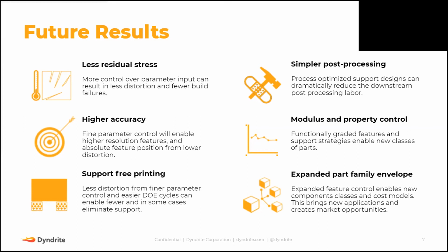Yeah, perhaps this is a sidebar. One thing we could probably do as an industry is standardize how we refer to things a little. So things such as stripes, checkerboard, meander, we refer to as scan strategies overall for the 2D area. What we refer to at Renishaw as a scan style is individual vector types. So whether that be borders, hatching, downskin borders, downskin hatching, and so forth.